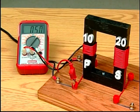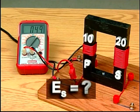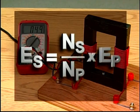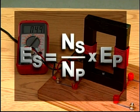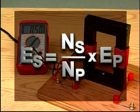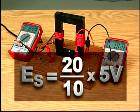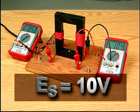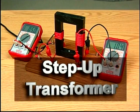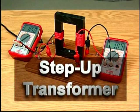For example, there are 10 turns on the primary and 20 turns on the secondary. If the primary voltage, E sub P, is 5 volts AC, what is the secondary voltage, E sub S? Solving for E sub S, the equation is E sub S equals N sub S divided by N sub P times E sub P. Substituting the values, E sub S equals 20 turns divided by 10 turns multiplied by 5 volts. Therefore, voltage E sub S equals 10 volts. Since there are more turns in the secondary than in the primary, the output voltage is increased. This is known as a step-up transformer.